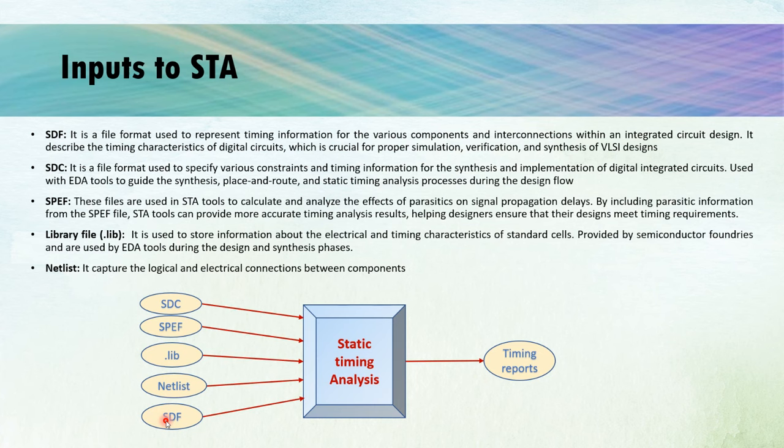SPEF files are also used to calculate signal delays caused by the parasitic capacitance and resistance. This information is really crucial in estimating the signal arrival time and whether that signal is meeting the timing constraints or not. Note that the timing constraints I'm talking about are mentioned in the SDC files that I just discussed.